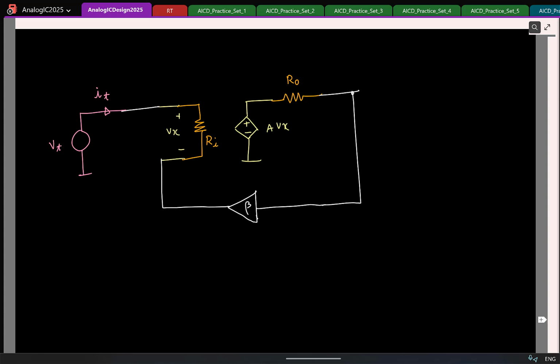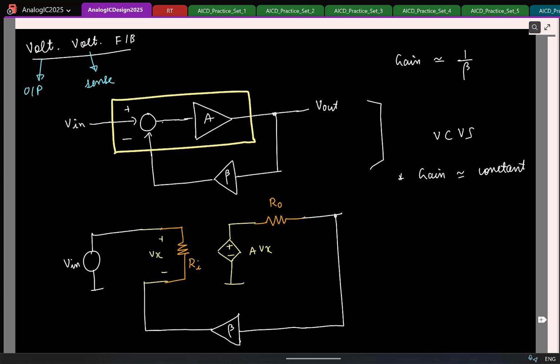See, in my negative feedback system, as long as the gain A is really large, what can you say about the input and the feedback signal? Same. The idea is, if it is negative feedback, this gain A is going to be really large, so the error signal is small, which means the input and the feedback quantities must be equal.